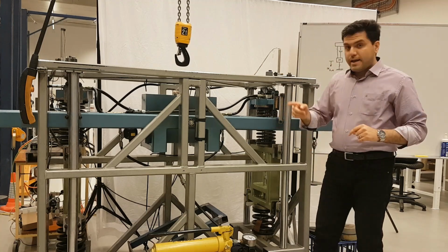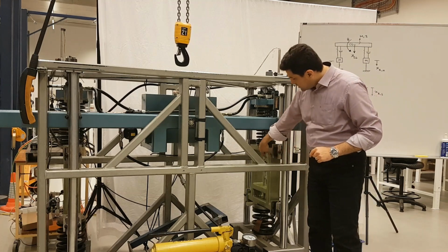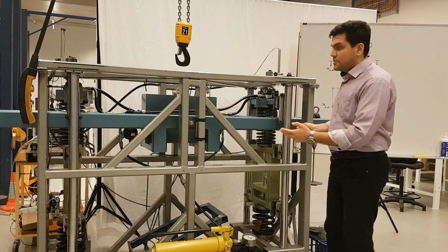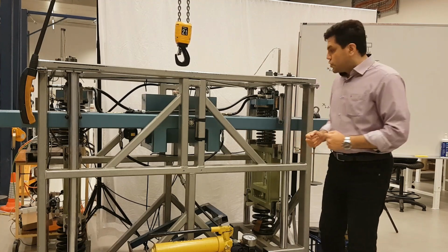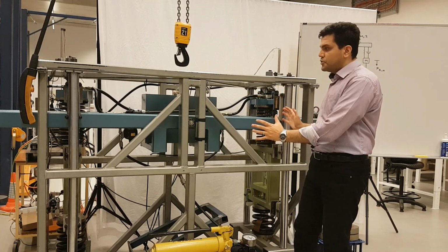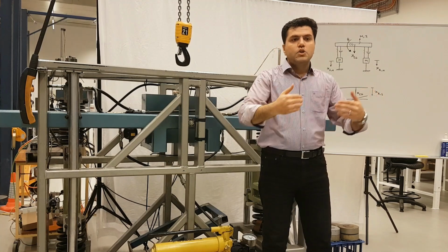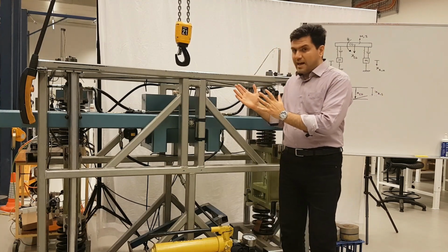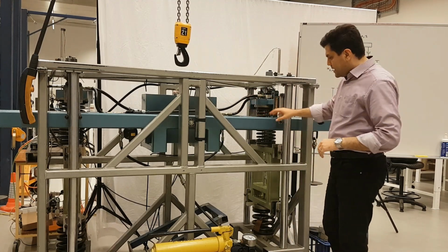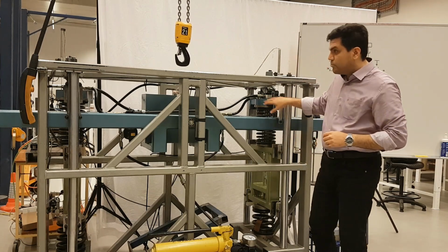The spring mass is sitting on another 2 masses: this green mass, and on the other side, another green mass. These 2 masses represent the mass of the tires. Just assume that this structure is the front part of the vehicle. So this is the half car, the front half of the vehicle. The spring mass is sitting on the tire masses using springs and dampers on both sides.